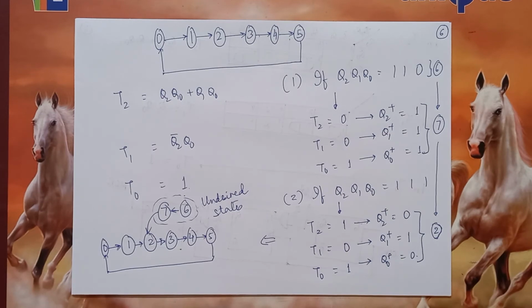You can forcibly make them 0, or you can assign those as don't cares. But if you are assigning don't cares, make sure you know which will be the next state if those undesired states are ever encountered. It may so happen that the undesired states may keep oscillating between themselves and they may never come back as part of the main chain. In that case, it is disastrous.